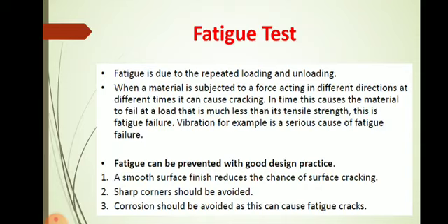Fatigue can be prevented with good design practice, so that a smooth surface finish reduces the chance of surface cracking. Wherever surface defects previously exist, due to vibration, misalignment, other factors and cyclic load, fatigue failure will occur.